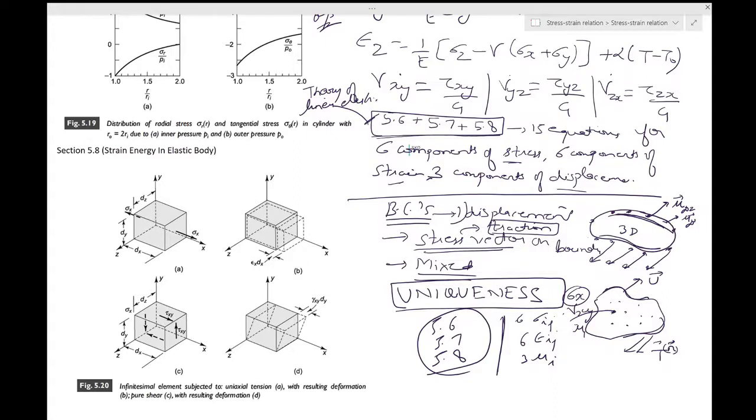And your linear elasticity, isotropy, small strain, all those assumptions are valid, meaning equations 5.6, 5.7, 5.8 hold on every interior point. And they will also satisfy the boundary conditions clearly. Okay, so that's the uniqueness of linear elasticity solutions.